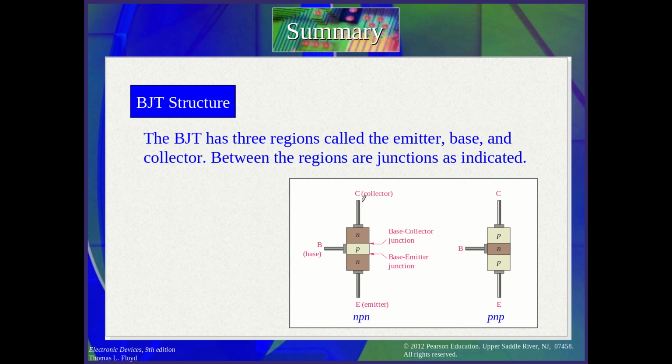Now let's see the normal operation. I want a normal operation for the transistor to work. In the normal operation, I should keep the junction between the base and the emitter forward biased, and the other junction reverse biased. Forward biased means that it should cross 0.7 volt.